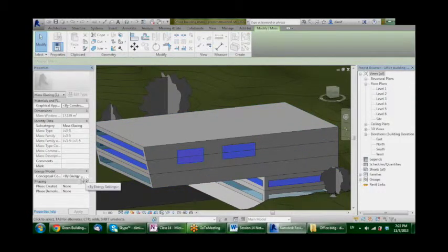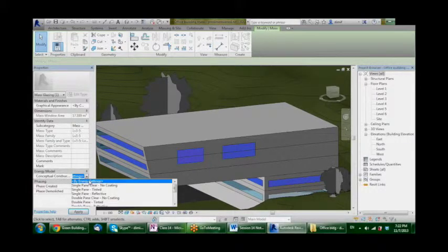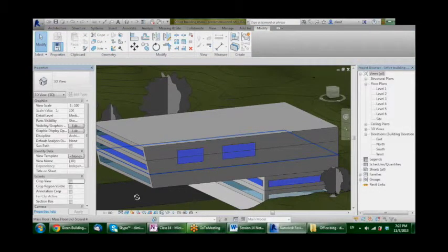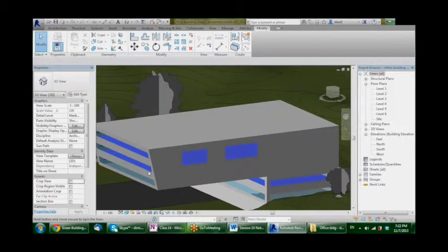You can change the window material and everything in the conceptual construction here, left-hand side on your browser, and you can either keep it by energy settings, or you can select specific window types for those windows. By all means, the same goes for all other pre-dimensioned windows that are already there.